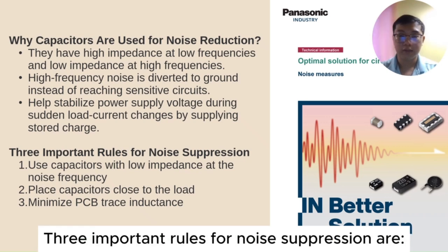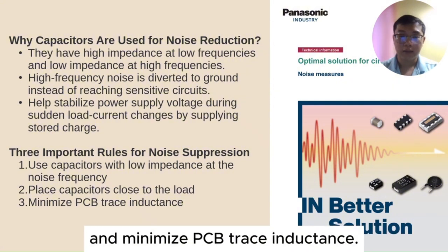Three important rules for noise suppression are: use a capacitor with low impedance at the noise frequency, place it close to the load, and minimize PCB trace inductance.